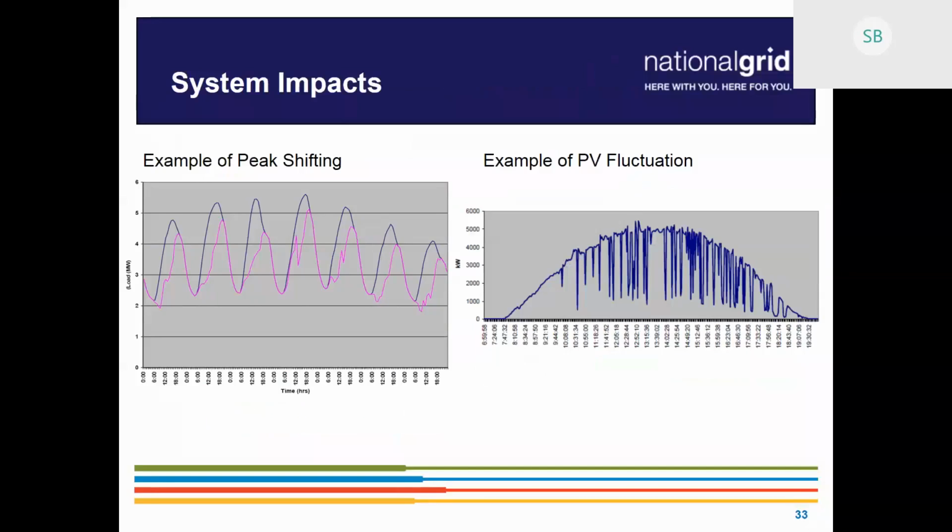And the one on the left is showing how the DG on our feeders has shifted the peak a bit. It reduces the peak and shifts it to a different time of day. So it does call for a different kind of planning approach and analysis. It is reducing overall load, but that isn't always necessarily just a great thing. It's good. It does reduce load.